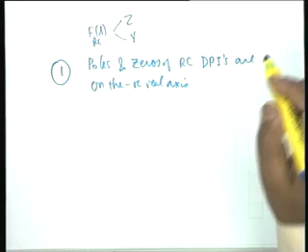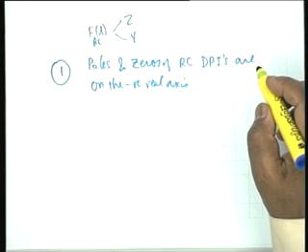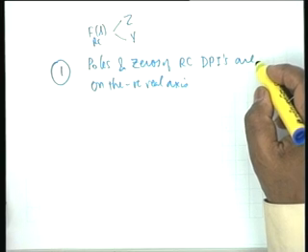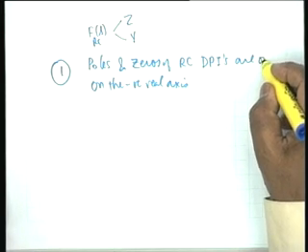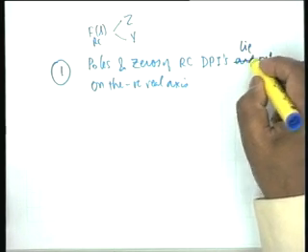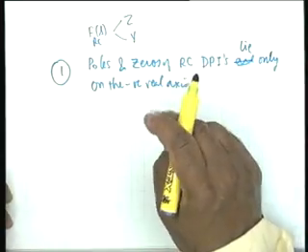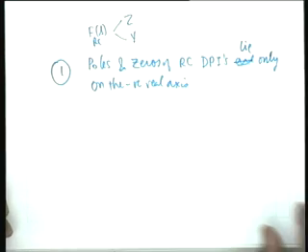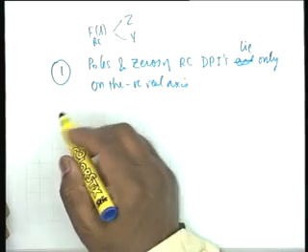impedances are on. No, this is not a strong statement. Let us make it stronger. They lie only on the negative real axis, nowhere else. Let us make it a strong statement. Poles and zeros of RC driving point impedances lie only on the negative real axis. Second,